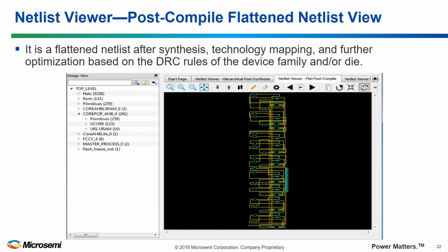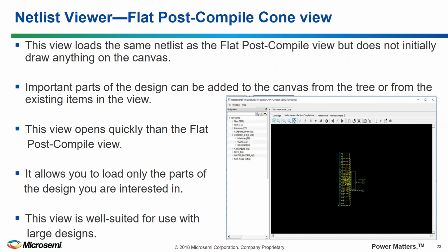After you've synthesized, you can open the post-synthesis hierarchical view and see the kind of blocks that were used. For example, if I was writing a description of a FIR filter and trying to use the math blocks, in this view I might just see symbols indicating additions and multiplications. In the next view I could see these big boxes might be the math blocks, and I could make sure that the math block looked like it got used, and I could drill in and see, did the registers in the math block get used, and things like that.